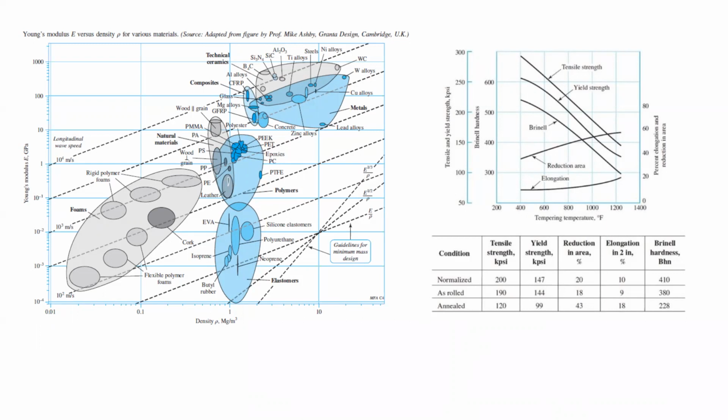So it's a loaded question. It's like there's some materials like ceramics that have a higher stiffness but lower density, right? So per the standard requirement, it should be the better material. Why don't we just make everything out of some kind of ceramic? Yeah, so this is kind of the pitfall of only choosing like 2 parameters to select a material with. You kind of forget some of the other important properties. So ceramics are bad in some cases because they're brittle. So they have a really high yield strength, but they don't have much energy that they can absorb before they basically permanently just separate, right?